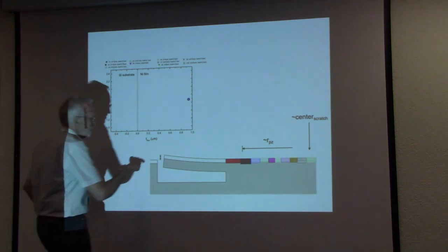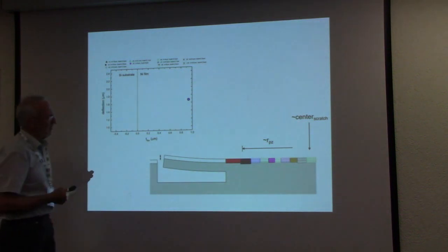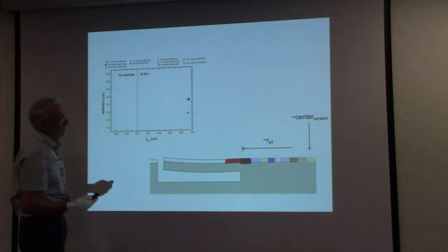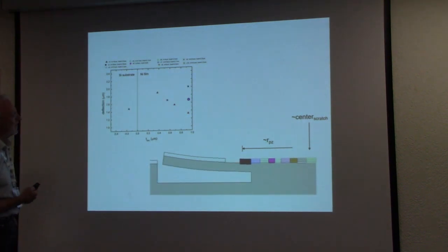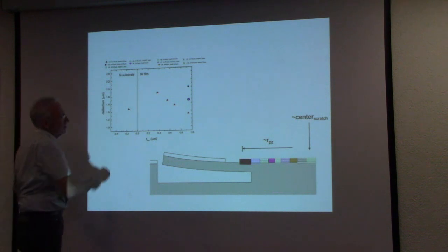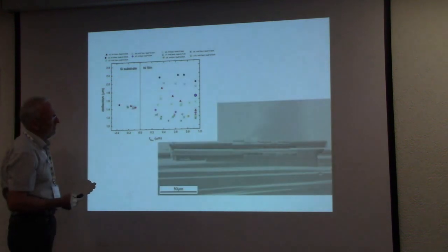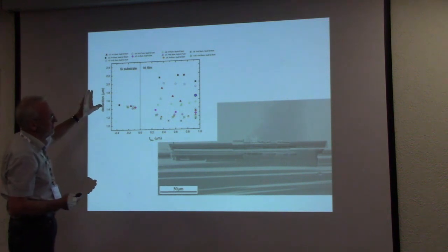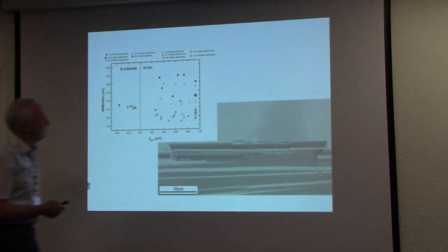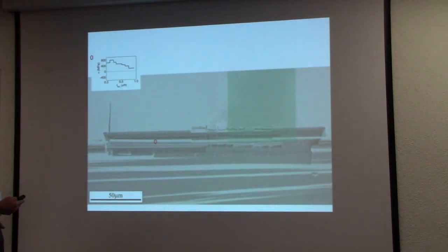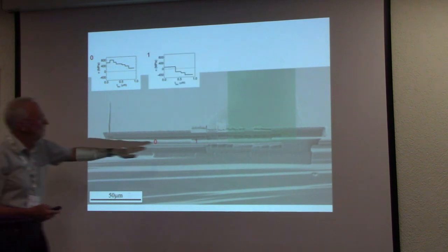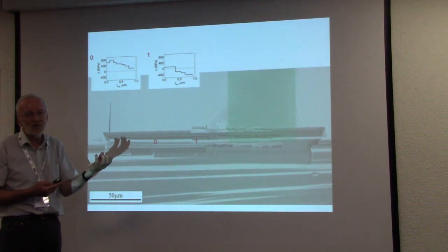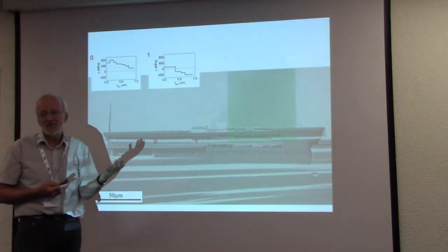The same technique is now used. What you see here, we simply undercut this bending beam and then remove one after the other. We get the deflections. Undo this again and again, and so you get a large number of deflections for all the cutting processes, and then you can simply calculate the residual stress in each volume element. And so you can really get a 3D picture of the residual stresses.